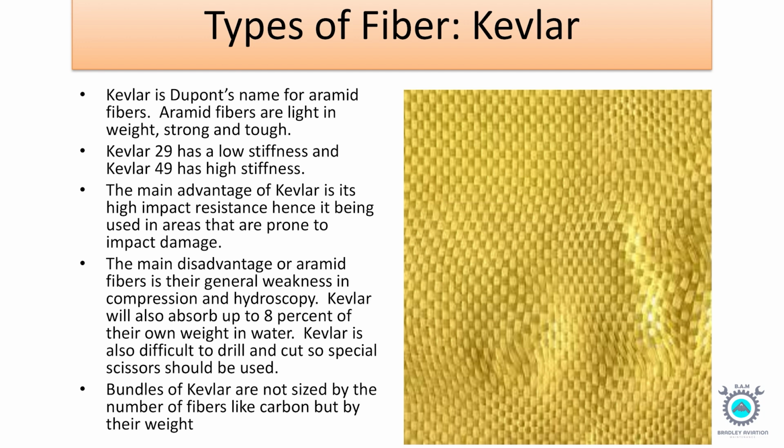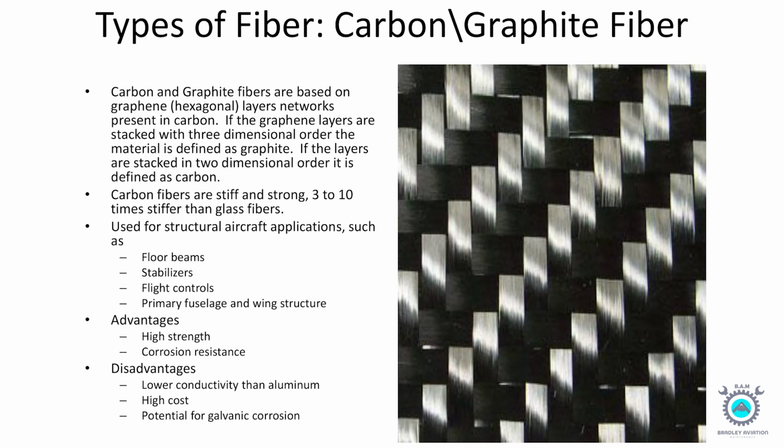Kevlar is also difficult to drill and cut, so special scissors should be used. Bundles of Kevlar are not sized by the number of fibers like carbon, but by their weight. Types of fiber: carbon graphite fiber.